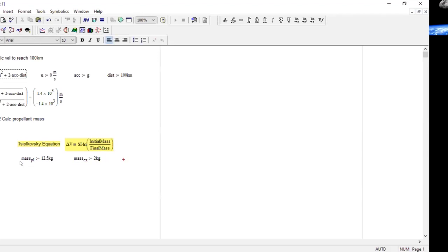The specific impulse, again, you may have different units for specific impulse, but there is only really one sensible unit. The specific impulse is the amount of impulse you get, that's the number of Newton seconds you get for every kilogram of propellant. I know a lot of people would use seconds as a unit of specific impulse, but it's a silly unit, really.